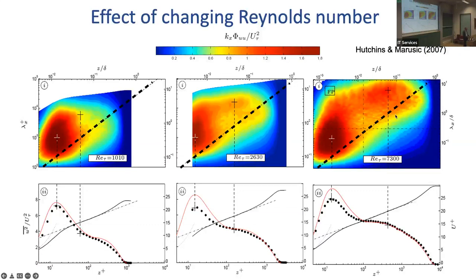Essentially, these are the attached eddies. They make up these complex features that define a high Reynolds number boundary layer. I've marked here FP for footprint, because we see that this signature, even near the wall, has this very large scale signal which extends down to the wall.